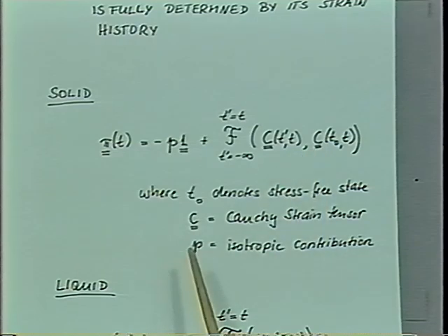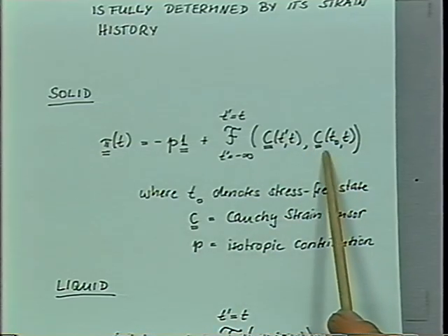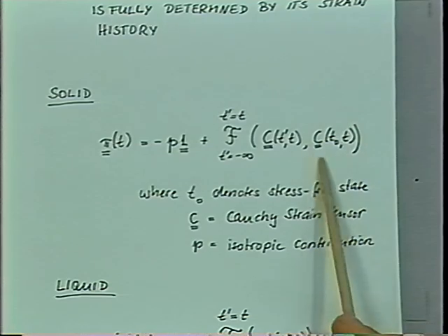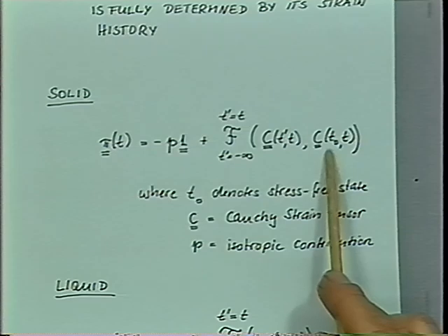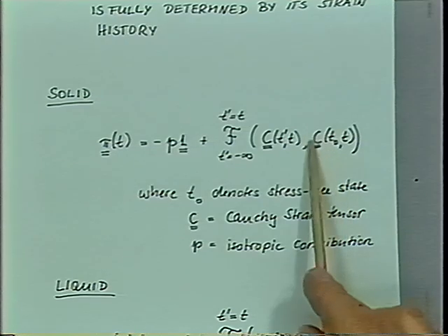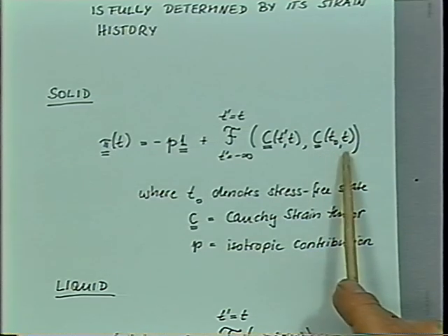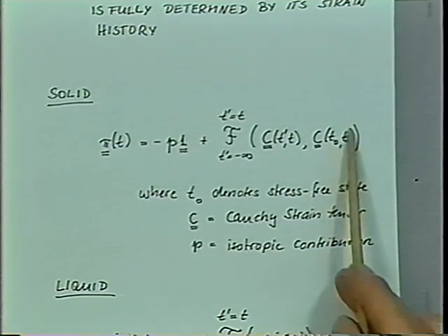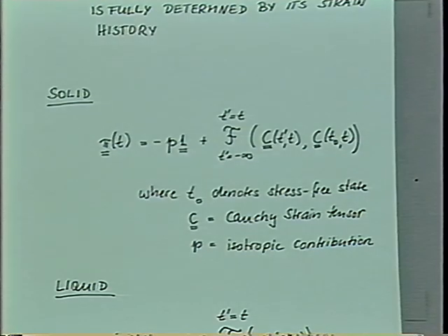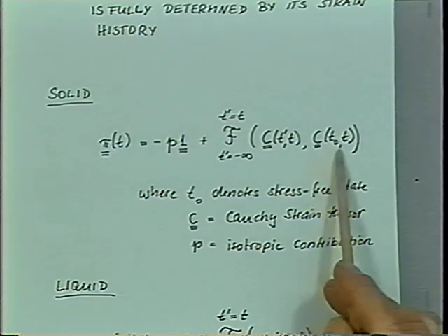That's what we would like to know. And in case of a reference state where the material is stress-free, we can use that stress-free state to define strain tensors. In the case of a solid, there's always a stress-free shape to which the solid material will return when we let go. So we can use that as the reference state.